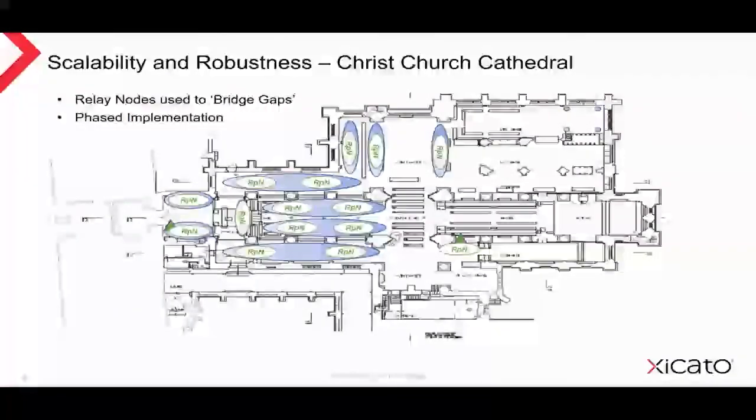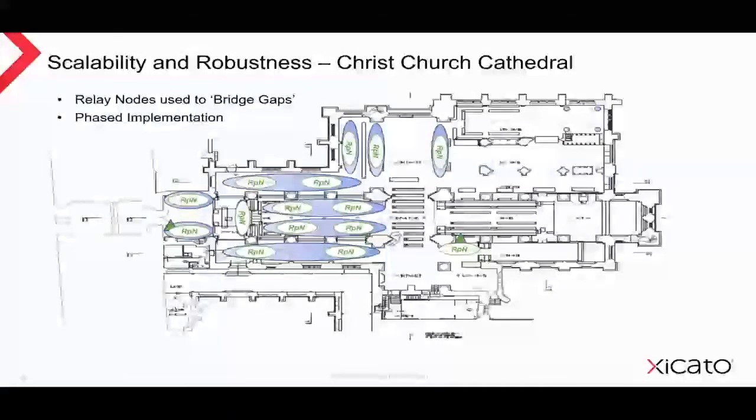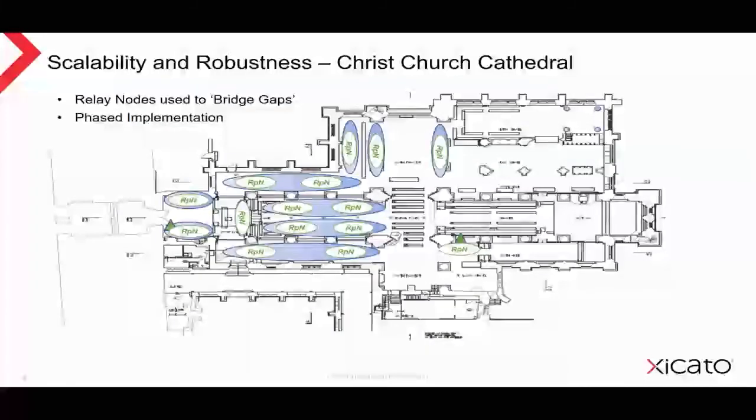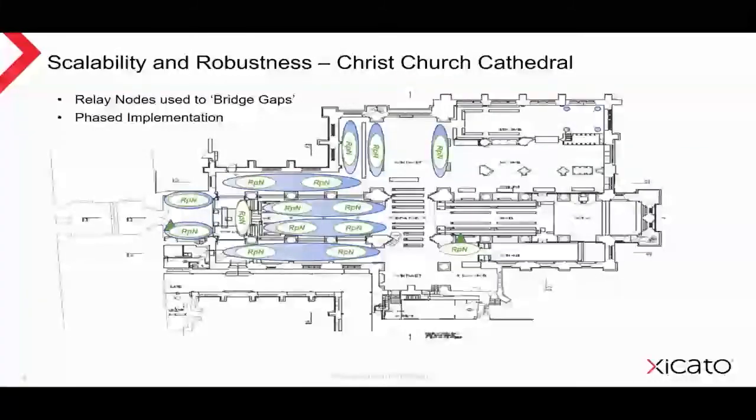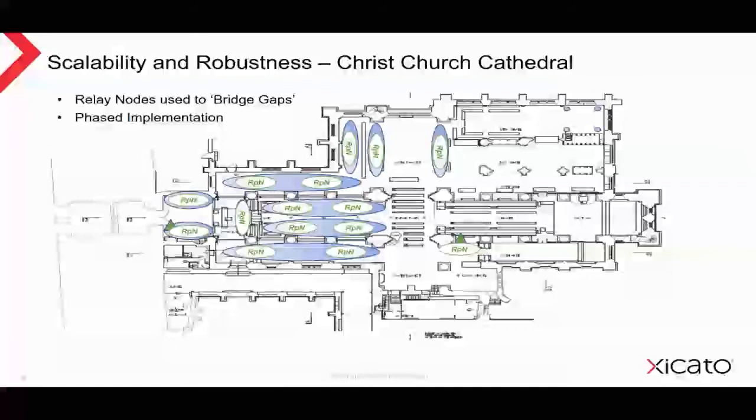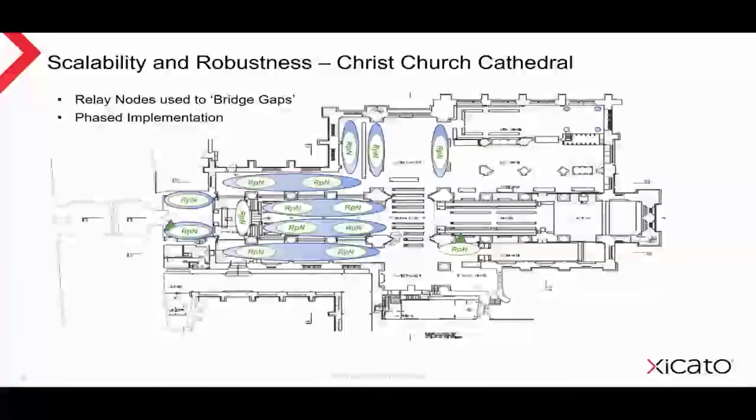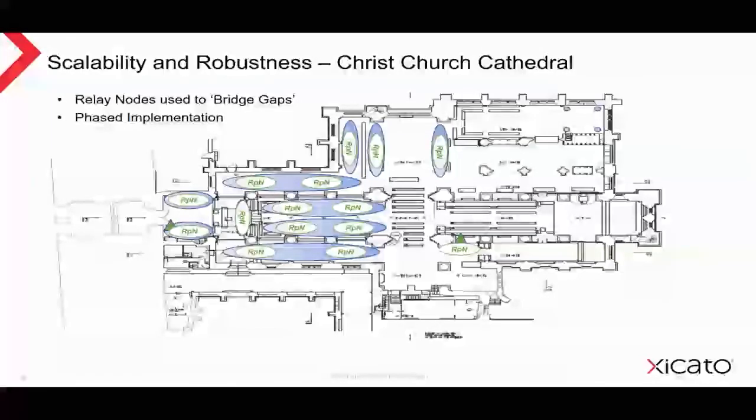The usual approach here would be to configure a series of lighting nodes and possibly BLE switches as repeaters to create our mesh network. These repeaters receive commands from the switch panel and pass them on around the network, thereby extending the network reach. Obviously, this relies on each node being within the signal range of its neighbor, and best practice is to configure multiple repeaters such that there is no single point of failure.